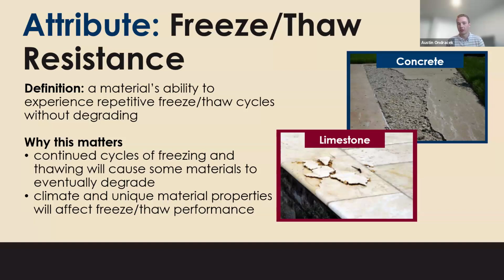Now, depending on where you live and what market you are in, I know in my market, kind of in the Northwest, this is a big topic when you talk about freeze thaw. That's something that really makes a stone or a man-made material's ability to withstand it quite apparent after a few years of being able to have it tested. When you talk about using both a natural stone or a man-made, both can be susceptible to a freeze thaw cycle. It's appropriate to know what stone to use for which application. Are you doing a vertical application, a horizontal application?